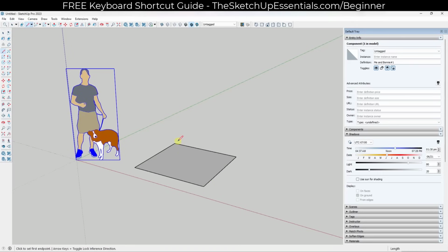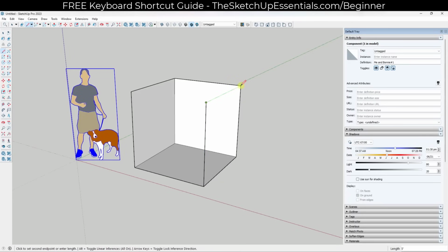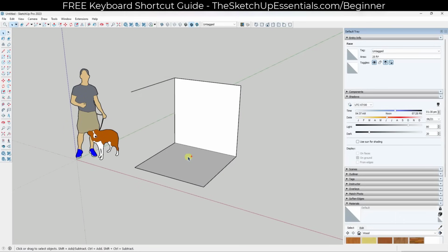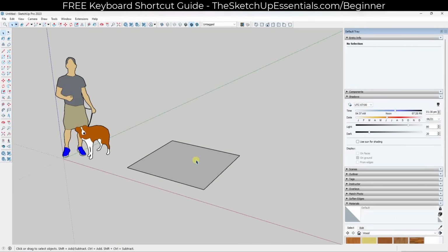Because what we could do is draw a line up 5 feet, draw a line across 5 feet, and we could just do this manually for all of our sides, right? So I could do this. This is a valid way of doing this, but it's very time consuming because I have to draw all of these edges in here like this. And so that's a little bit problematic. So what we want to do instead is take this face and extrude it to 3D very quickly.